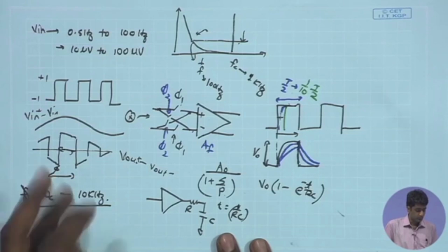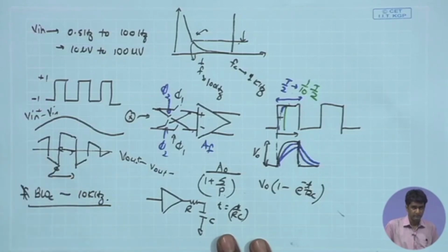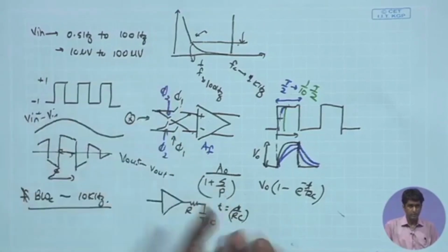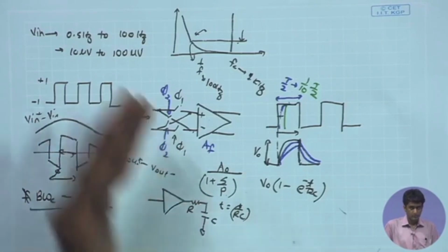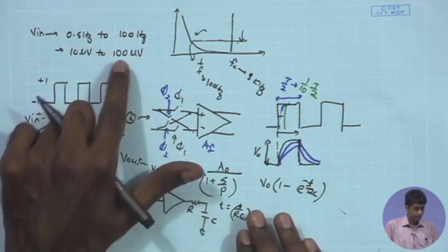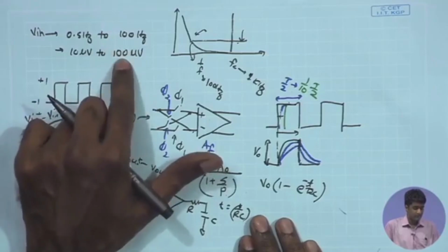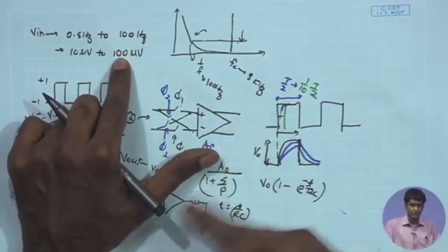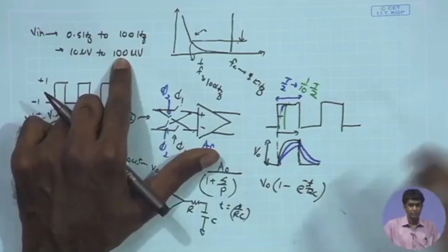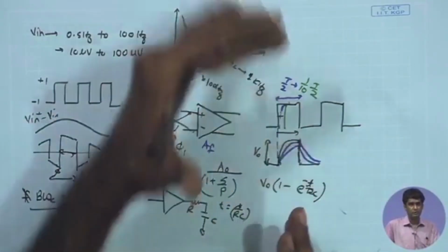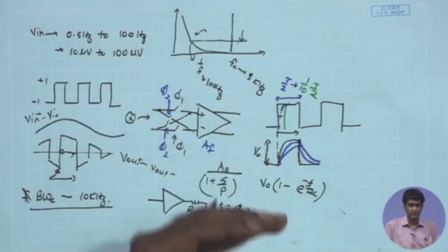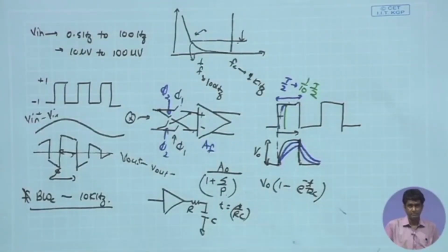and now we need to go for the open loop bandwidth and the gain bandwidth product. So, the gain that was expected was the closed loop gain overall, say we are going for around 10 to the power of 4, that is what we estimated. So, for example, if you have a maximum signal amplitude of 100 microvolt and the closed loop gain is 10 to the power of 4, the maximum peak to peak swing that you can have at the final stage is going to be around 1 volt. So for a 2 volt VDD, 1 volt peak to peak swing can still be tolerable if you design the amplifier properly so that the output stage swing is maximized.